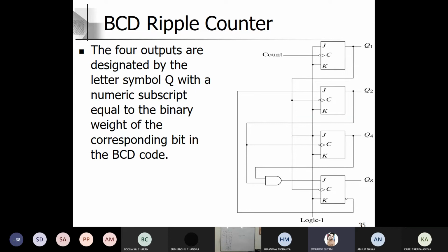Yeah, a ripple counter is an asynchronous counter only actually. The only thing is they are trying to specifically tell here that this asynchronous counter mostly works from 1 to 0 change, and it's a negative edge clock pulse. That's why the small bubble has been elevated, because this observation earlier we have not seen, right? Similarly, they have proposed so many counters. This is just a proposition. In fact, this is also generation of sequences only, but this is a different proposition.